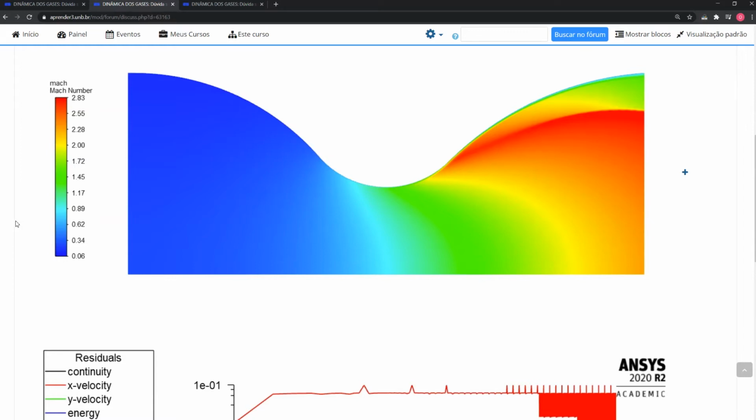Yeah, please do not forget to use area weighted average, because the area Mach number relations you used in work one are giving average values. So in the simulation, you also need to have average values of the flow, not flow properties on the wall or on the axis. It should be an average, taken by the area average tool in Ansys Fluent, or using the console command which I showed in the video to take the average along the axis. Both of these operations are equivalent, and you can use one or the other. You know which is better for you, you choose and you use.